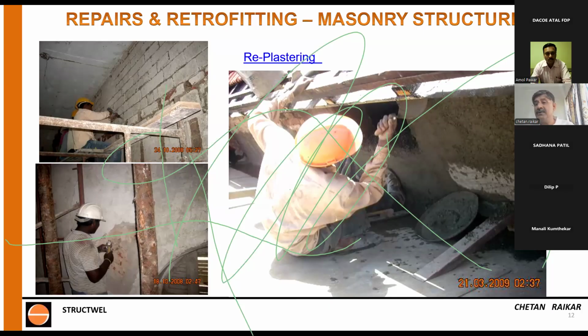Raking is extremely important. See, raking means if this is a brick masonry, and if you do not rake out the joints, how does the new plaster stick to the masonry? Because as soon as you rake out the joints, raking is where you make deep impressions of 5 mm, 7 mm or whatever, so that the new plaster, once you apply, it gets a grip into the masonry. It gets grip every 10 centimeters.